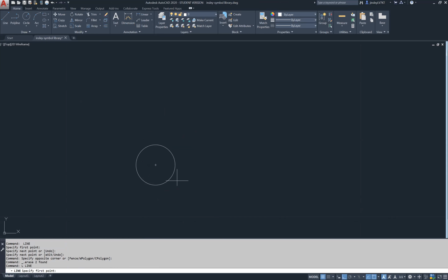You can see that with my AutoCAD we have these object snaps displaying themselves. There's the center point of the circle, where the green circle is on my screen. If I hover, so there's no clicking involved, over top of that center point, AutoCAD should place a marker. And now you can see that green marker.